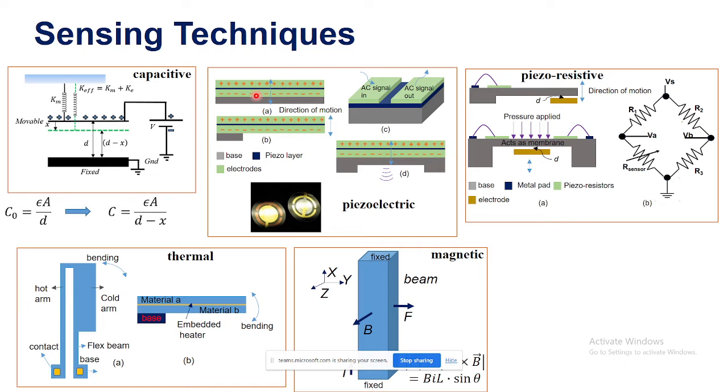Where is the direction of motion? Because the material is supported by the bottom plate like this, the motion is indicated by the arrow. In this structure, the base is supported here and it is simply a cantilever. Once we apply force, the charges will be created and the motion will be in this direction, because this is the maximum displacement point and this is the minimum displacement point.